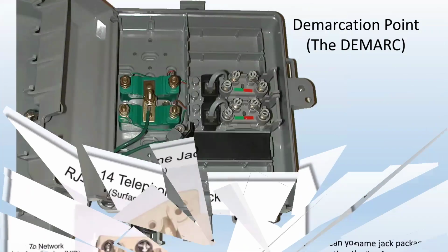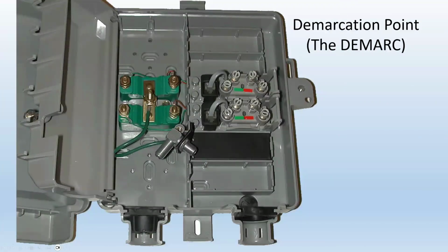All right, now here is a demarcation point, something that you can see on the side of the house sometimes. How does it work? The lines are coming from the city here, and they're connected here. So you can see there's green here, and there's a red wire, and another green wire. So this demarcation point, as it is configured right now, is capable of receiving two lines or servicing two lines. So you can have two telephone lines coming from outside, and it will provide two telephone lines. How does that work? So these two blocks, those green blocks, and here's that little bolt and nut. That's a ground, that's connected to ground.